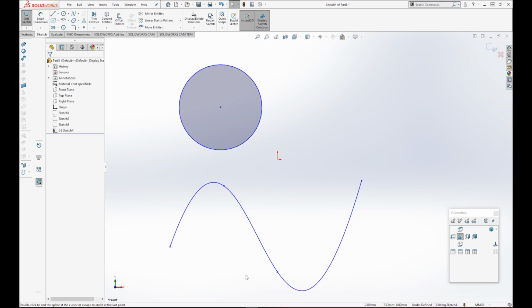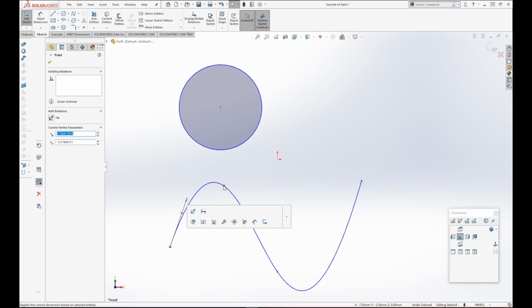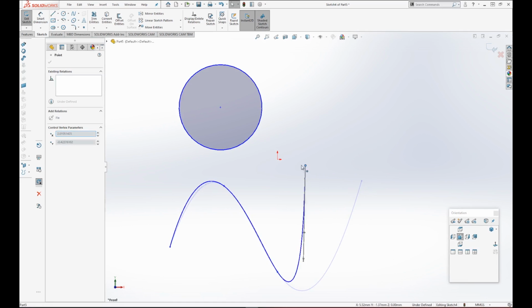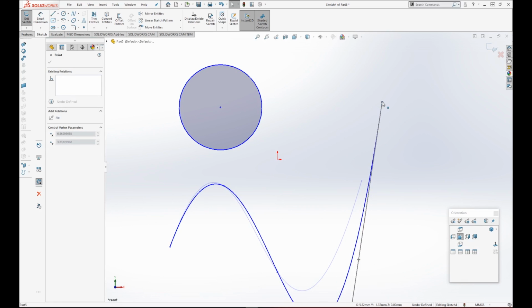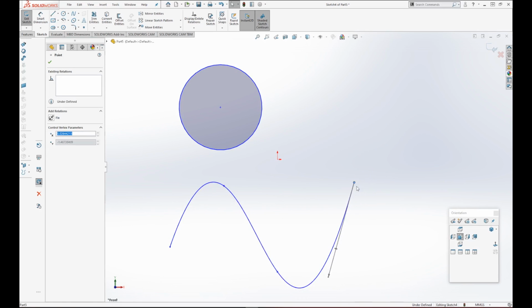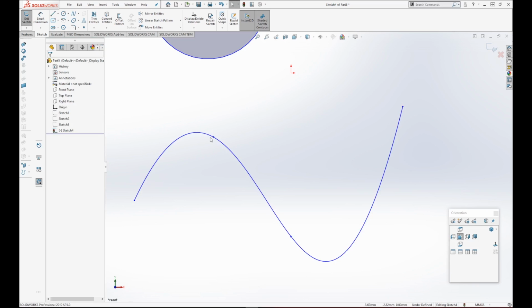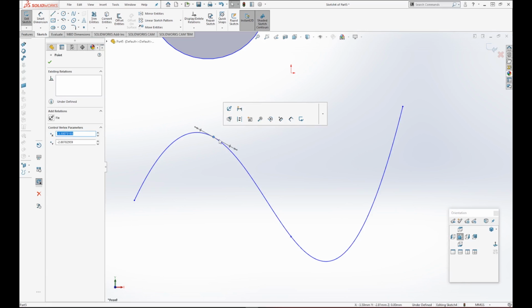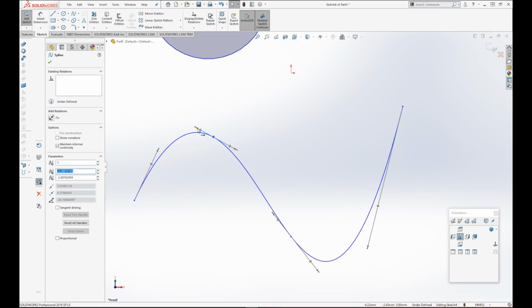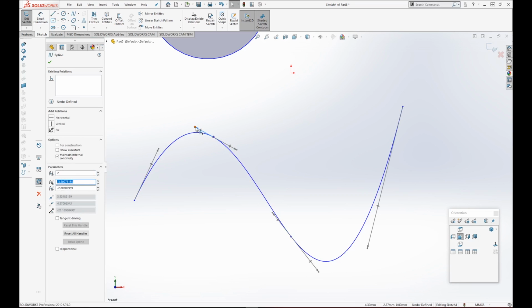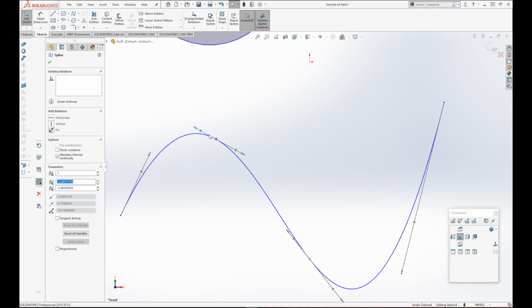You guys can see there's a couple points on this wave shape. There's these endpoints that are right here. I got one right here that I clicked, another one here, and the very last one. And now you guys can see that if I click on the endpoints, I can go ahead and manipulate my spline. If I select one of these vertex points, you guys can see there's these arrows that pop up. And within these arrows, there are 3 different markings: the diamond, the triangle, and then the center vertex point.